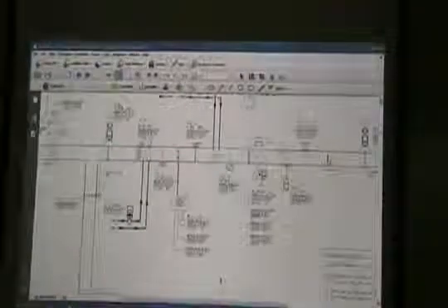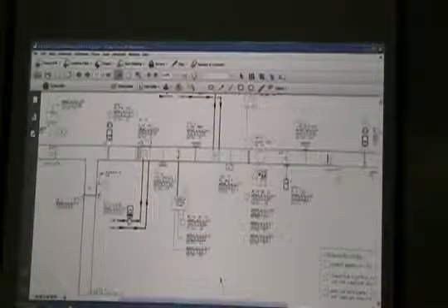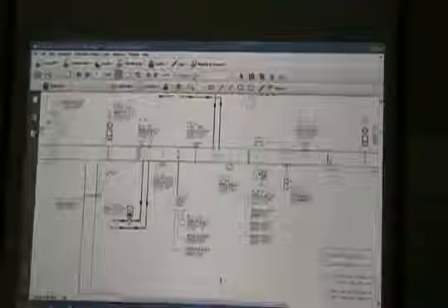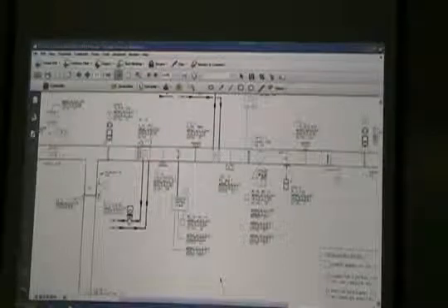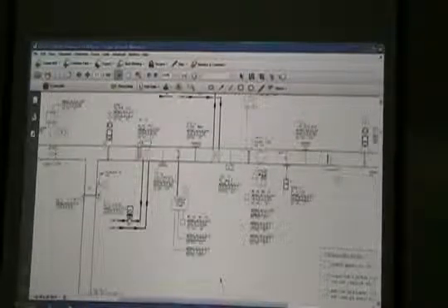Filters. The DDC panel should monitor the filter loading. Well, there's a set of filters right there, and there's a differential pressure switch. So that would be a digital input into our device. All that's doing is making and breaking at a certain pressure. So you listen to what he set it up at, no, he didn't listen to the pressure. Probably on a pre-filter, that's going to be a half of an inch to 1 inch.